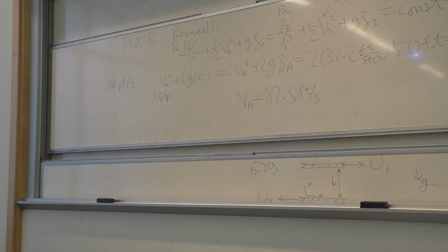That is no longer what we call a no-slip boundary condition, because when the air and water are at this common interface, both can be sheared. So the no-slip boundary condition will not apply. More information will be given in order to solve that kind of problem. Fluid-fluid interaction is a little bit different kind of beast that we are not prepared to discuss in detail.